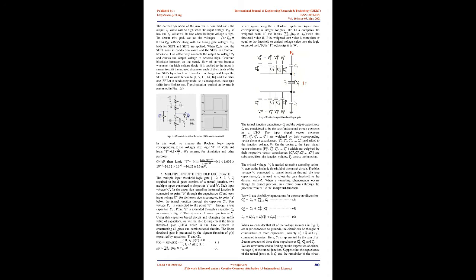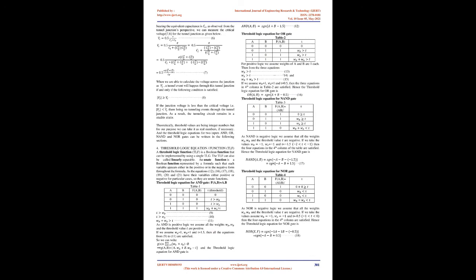The processing speed of a threshold logic gate, TLG, will be nearly close to the electronic speed. The single electron transistor, SET, and LTG draw the attention of researchers, scientists, and technologists to design and implement large-scale circuits for the sake of ultra-low power consumption and small size in different phases of applications. Tunneling events for TLG-based circuits happen when only a single electron tunnels through the tunnel junction under the proper bias voltage and multiple input voltages connected to the islands via small capacitors.